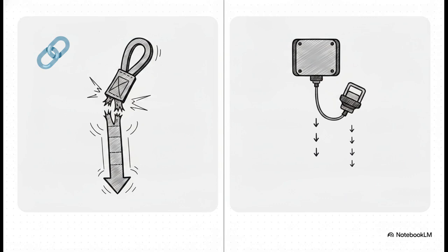You basically have 2 primary options here. On one side, you've got shock-absorbing lanyards. These are designed with a maximum expansion of 42 inches as they rip open to absorb your fall energy.